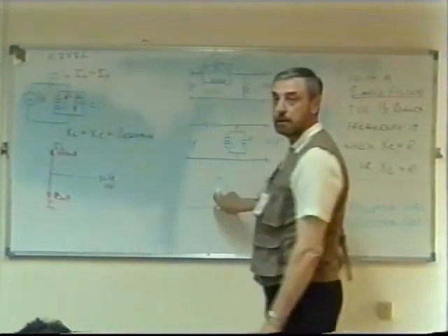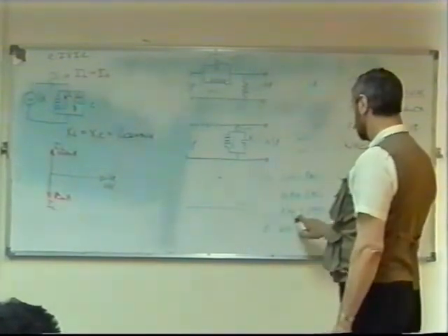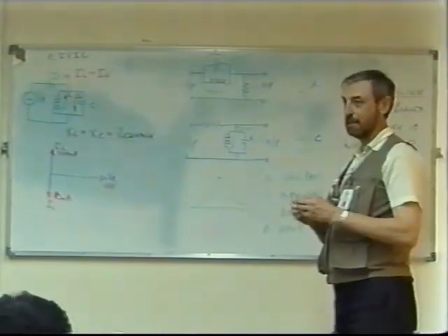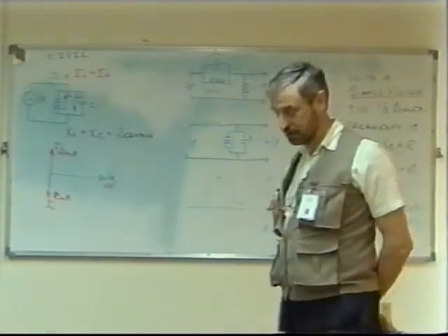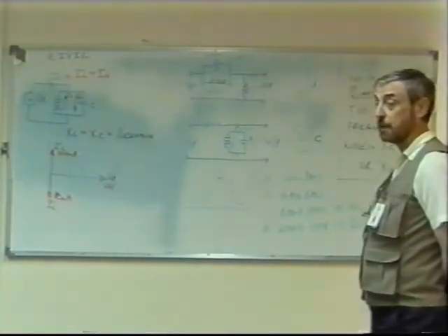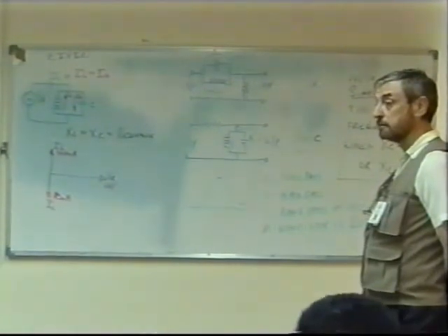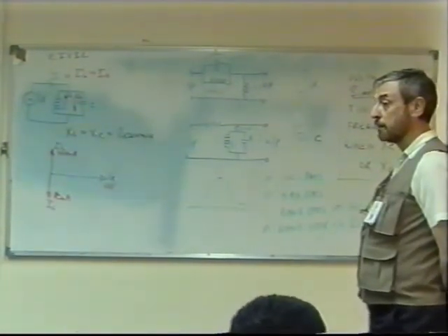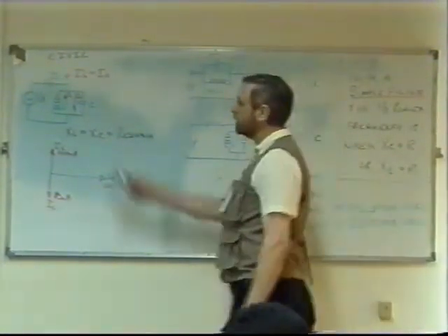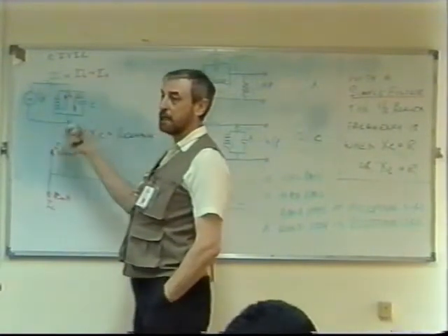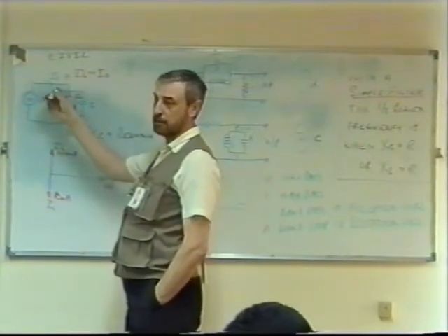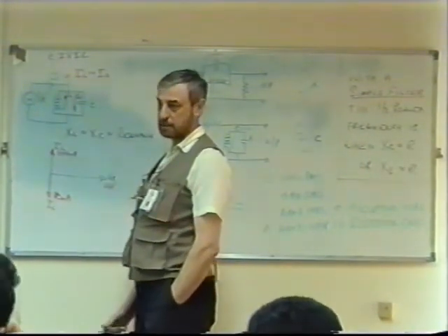So here, bandpass filter, which of course is C. Then from the circuit we have here, inductor and capacitor in parallel. You see, without the resistor, it's band stop. You've got to be careful. The way I explained it was without any resistor, and I just talked about the current flow, about whether it's a band stop or a band pass.